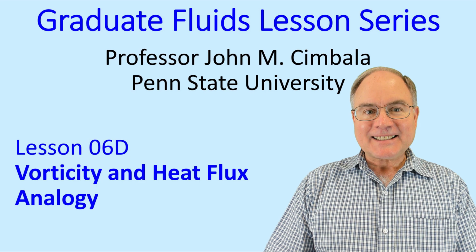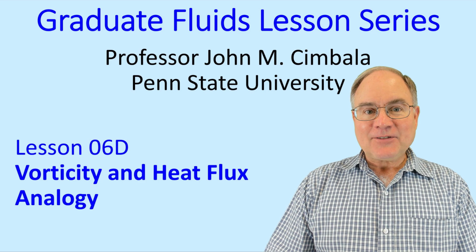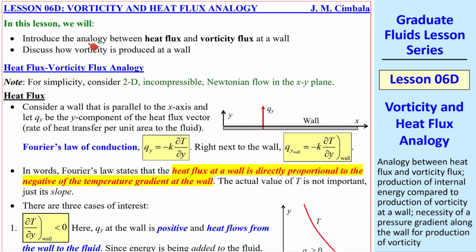Welcome to Lesson 6D, Vorticity and Heat Flux Analogy. In this lesson, we'll introduce an analogy between heat flux and vorticity flux at a wall. This will hopefully help us understand how vorticity is produced at a wall. For simplicity in this analogy, we'll consider only 2D incompressible Newtonian flow in the xy or x1, x2 plane.